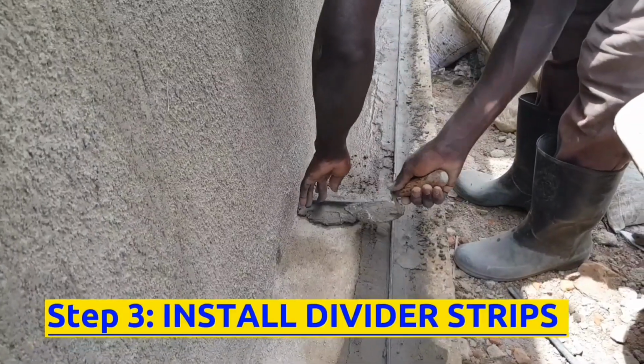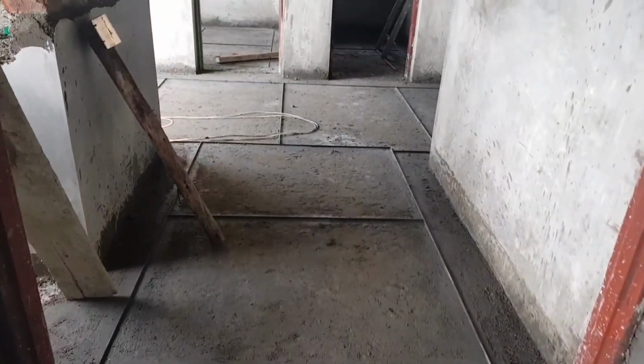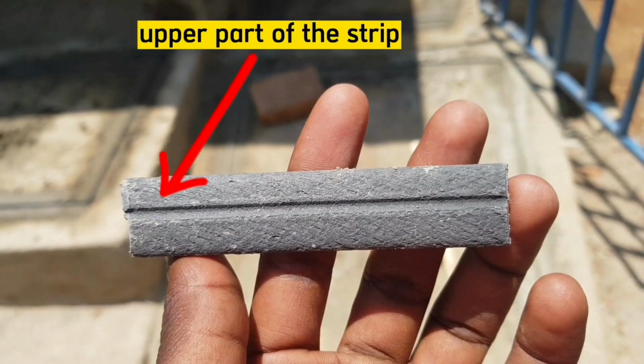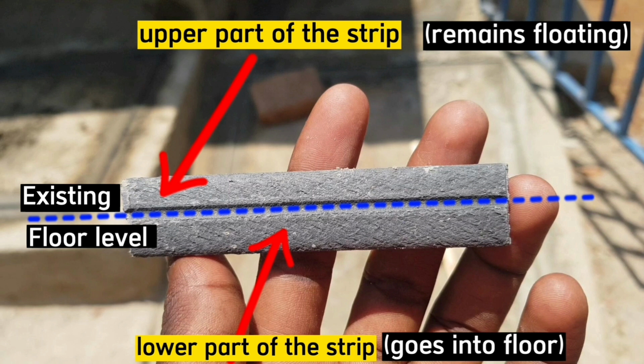The third step is to install divider strips into the floor. The spacing between the strips should not exceed 2 meters, and also install strips to demarcate different color designs. There are a number of strip colors, but the most common strips are black and white in color. A strip looks like this. This is the upper part and this is the lower part. This mid-row line marks the existing floor level. The lower side goes into the floor, that is below the floor level, whereas this upper side remains floating above the floor level to give the gauge for casting terrazzo.